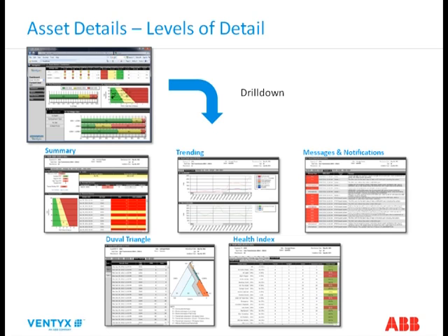You can see if there's a change in its performance or its rating when you process the oil, and so we can track all of that over time. And then the last slide, the health index. This is taking those 68 or as much information as you have available, different parameters, and then calculating what the health and condition of the asset is.